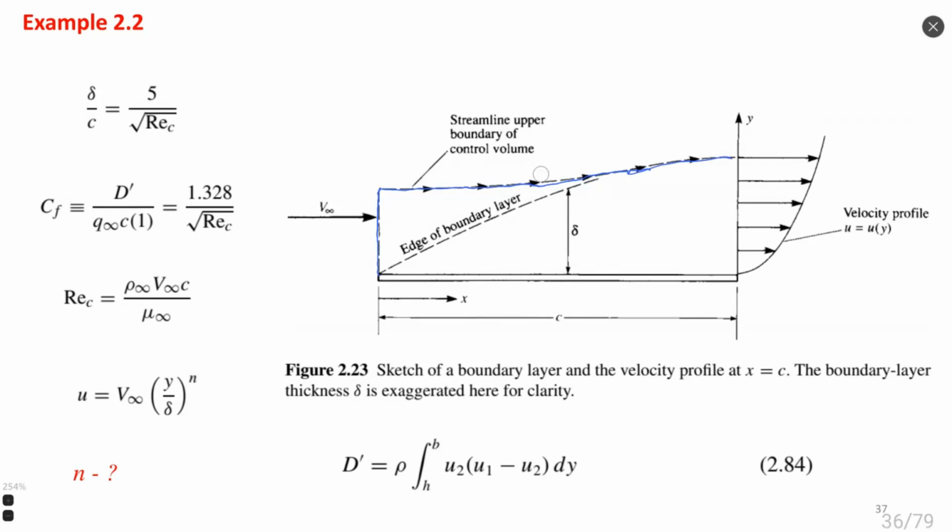Okay, I will probably delete this. It's not looking nice. The backside of our control volume is the velocity profile which we are looking for, and the lower side of our control volume corresponds to the body. At this point, we know that velocity is equal to 0 on the wall of the body. So our control volume is closed, and we can apply the equation of momentum to this model, and we can calculate the profile of velocity. To make the calculation of the velocity profile possible, of course, we must provide some experimental data.